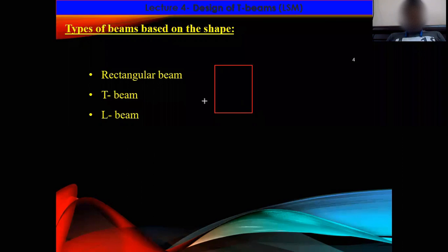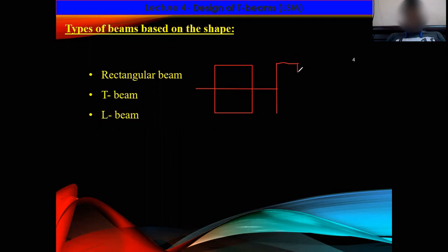And this is your neutral axis, that is the depth of neutral axis. If you observe the stress diagram as per IS 456 2000, approximately it will be a straight portion and a straight portion, then it will join as a parabola, right? So this is your tension force, this is your compression force, right?